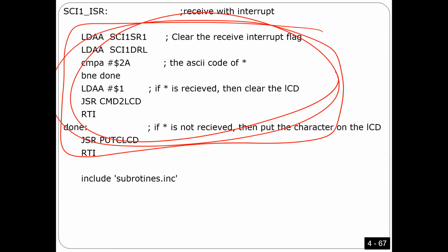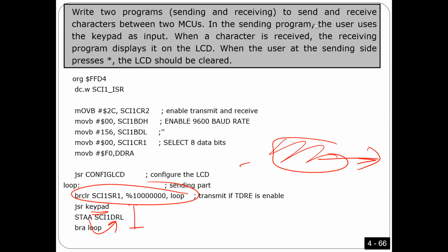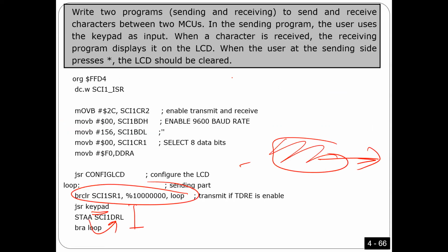So once this interrupt is triggered, this is the event. You remember the first word I used when I defined an interrupt was event. There is an event and we have to respond to it, right? The event now is receiving a byte. So after you receive a byte, I told you the byte you are receiving should be in this register. Just read it and then do whatever you want. That's what I'm going to do right now.